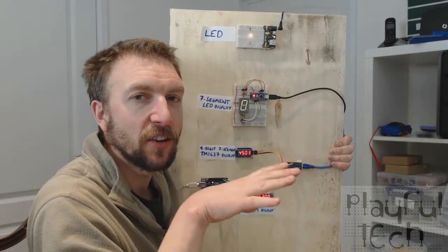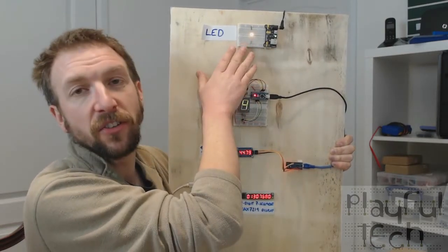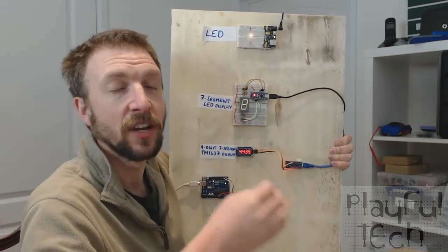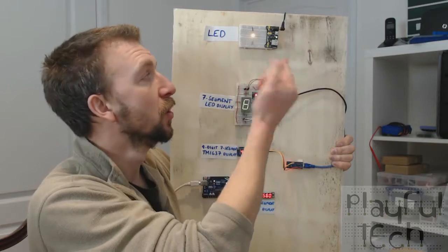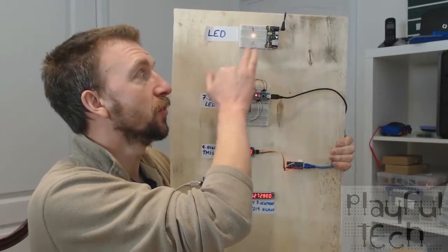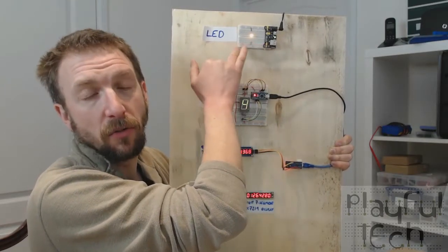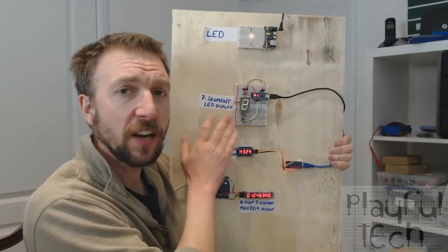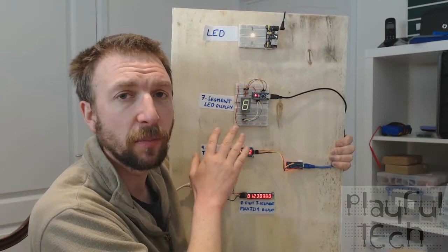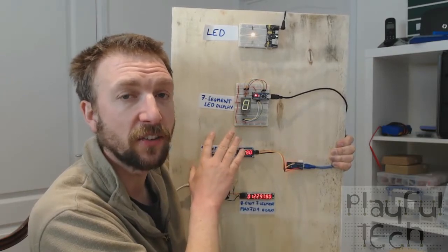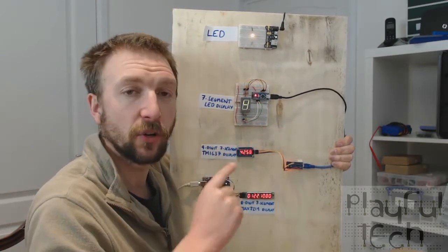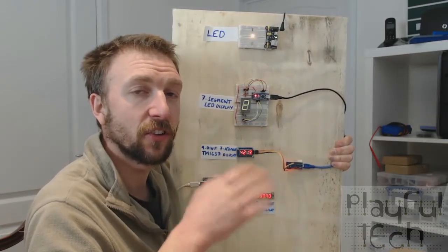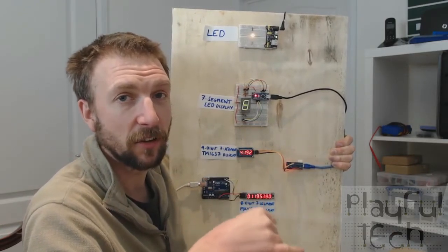Now this is where it gets slightly complicated. You're probably familiar with, on a circuit like this, you can have lots of components all going to ground and they share a common ground. Or you can have lots of components running off the 5-volt rail, and they all share a common 5 volts. And it's exactly the same with a 7-segment display like this. There's two sorts. You can get a common cathode 7-segment display, and you can also get a common anode 7-segment display.